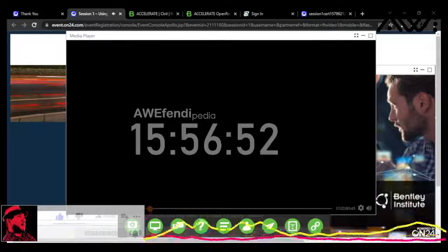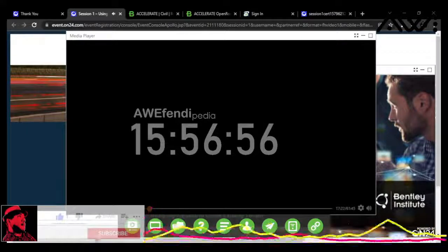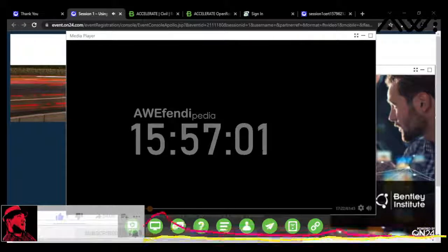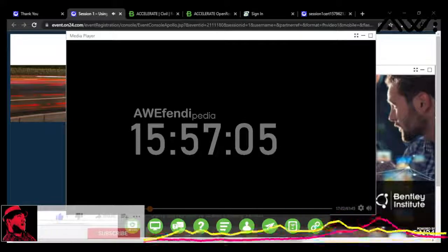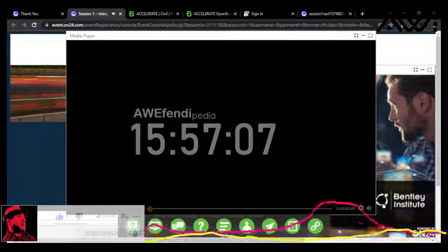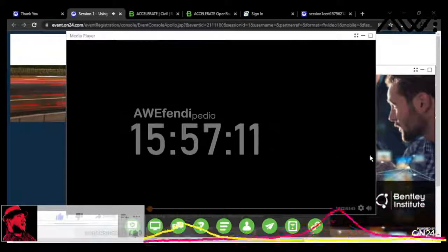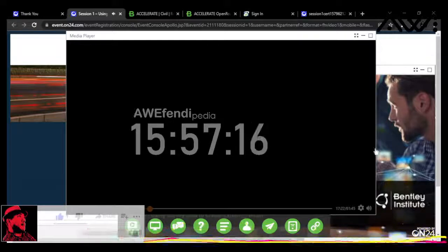So let's look for my IR field that we saw in that control text file. That's going to be this monument iron rod. I'm clicking on that, and if I look at properties, I can see that the alpha code is IR. So what's going to happen when I import that text file, it's going to come in to all of my feature definitions in my DGN libs. It's going to be looking for that IR alpha code, and it's going to assign that point this feature definition.